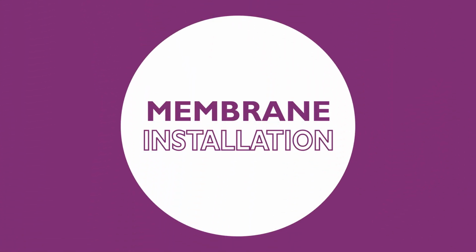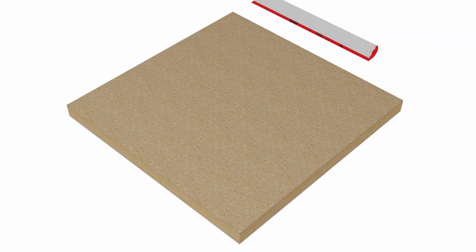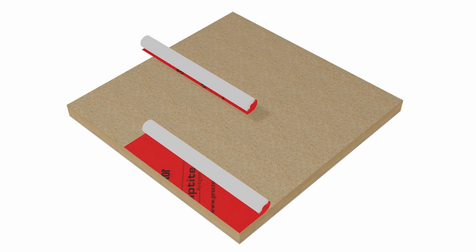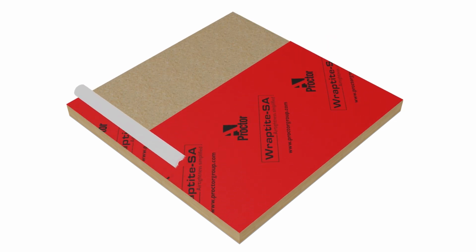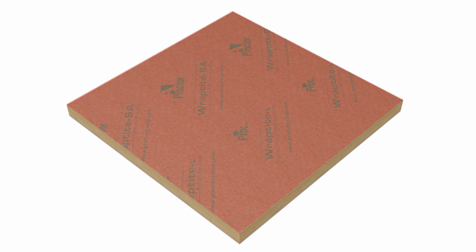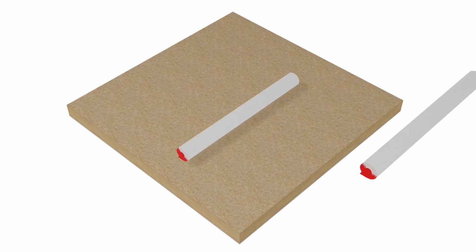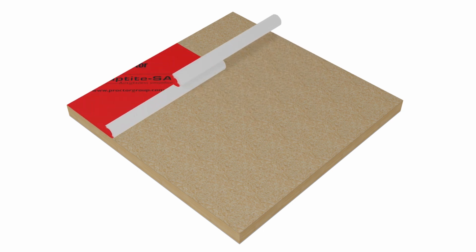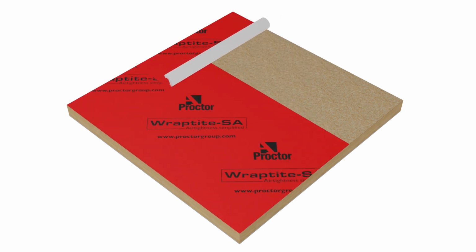In modular systems, incorporating an external barrier is straightforward and brings several benefits over traditional mechanically fixed membranes. The membrane can be applied to the panels in any orientation, and being self-adhered requires no mechanical fixings. The adhesion reduces the potential for membrane damage both during the module assembly process and while in transit to site.